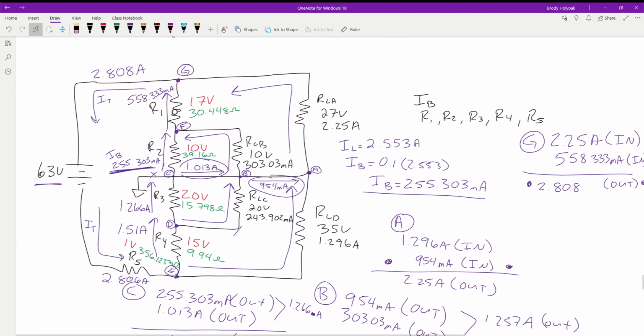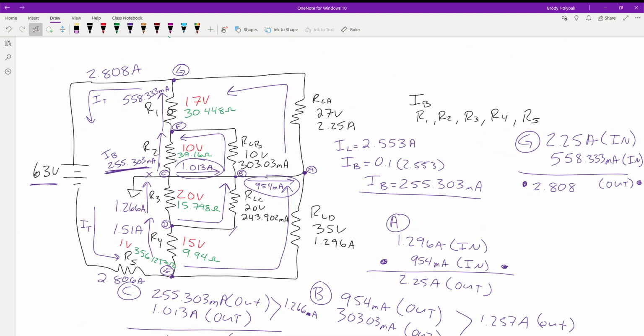And when we look at it, we know that we have the current here. We know the current's flowing this direction. So we know we can't have it here because this current's going to flow into it. So the only spot we really have is that resistor for our bleeder current. Flow into it too? Yeah. For R1? Not R1. You'll have the bleeder current and the load B current flows into R1. Okay, I get it.